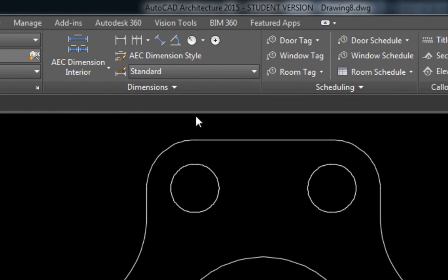We're going to come down here and select our circle. Now that will automatically create that center mark for whatever arc or circle that we created. It's quite a bit faster than the previous method. However, in some drawings you still need to use that previous method of offsetting the line 2 times each way and trimming off and all that.